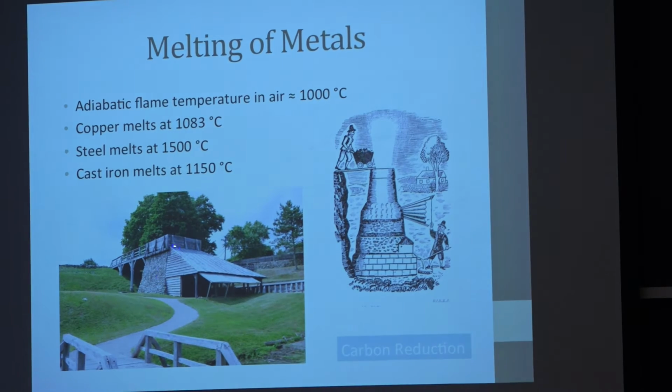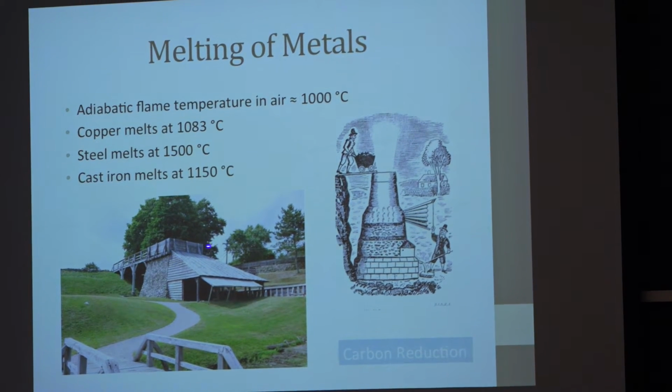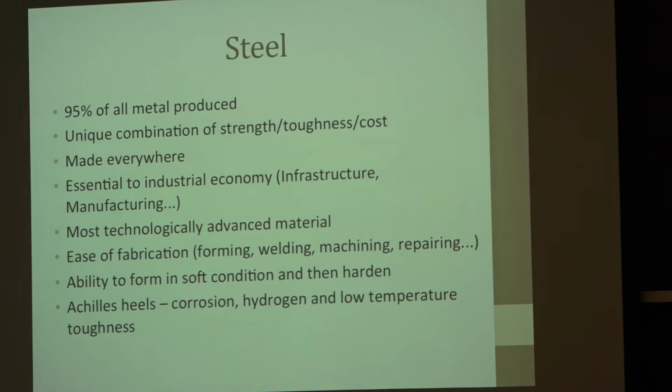And with the blast of air, you can pump that temperature up a little bit, plus in this confined space, if you insulate things. So here's the brickwork at Saugus. There's the thing where they bring in the wood. They built it on a hill so that they could be at different levels. And the casting floor is right down in here, which is basically just a sandy floor, okay? And they're going to cast the cast iron when they tap the furnace about once or twice a day. And typically it has to run continuously, okay?